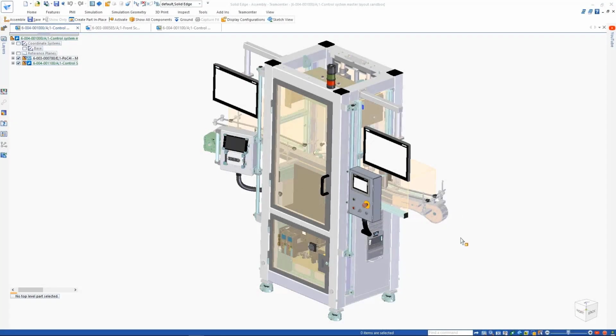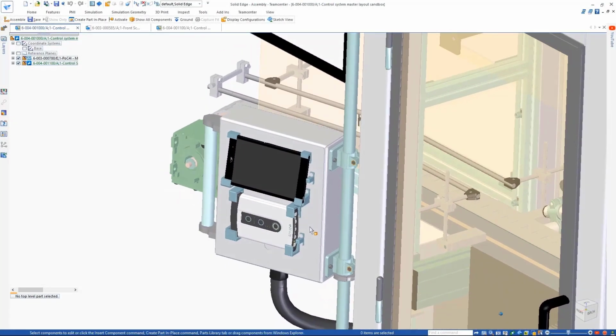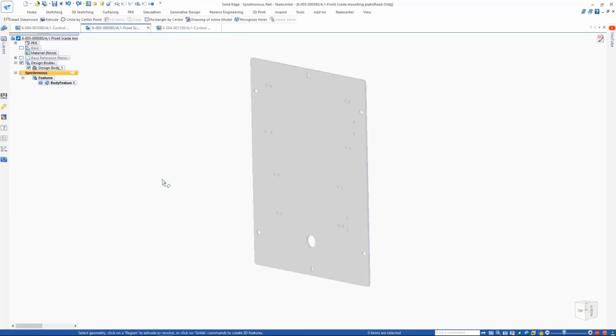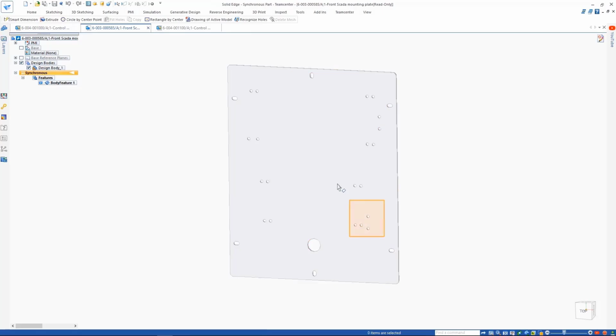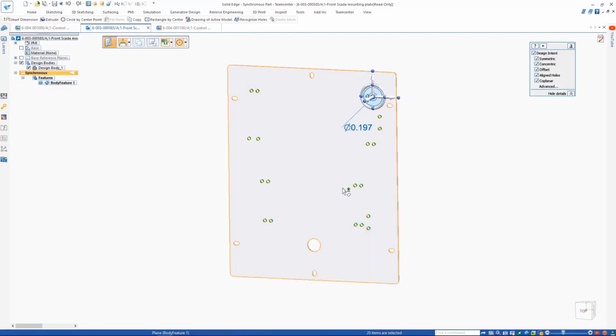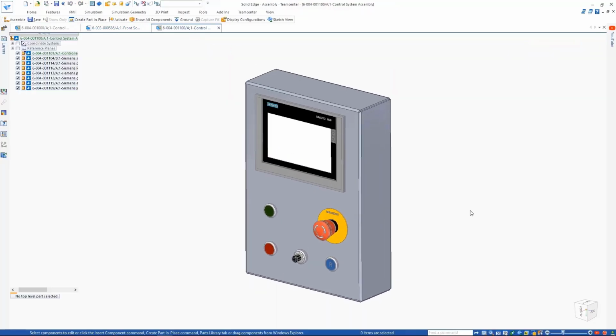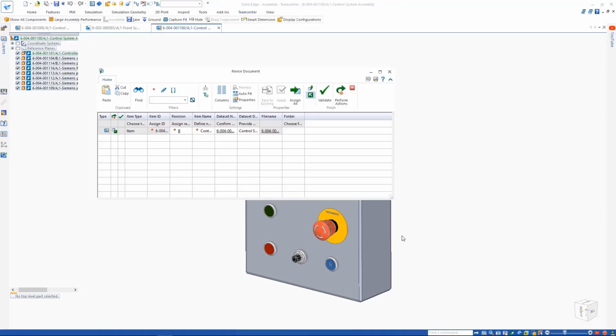Back to Solid Edge now. We have a design change that needs to incorporate the contents of the left panel into our newly designed right panel. To help here, we're going to use the power of synchronous technology, starting by copying the mounting hole locations from the left panel to the Windows clipboard. Then we can switch back to our new panel and make the desired changes.